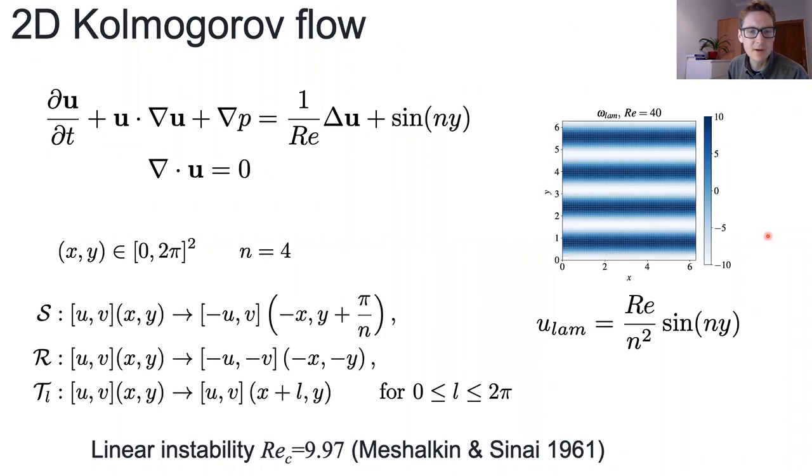So I'm going to study 2D Kolmogorov flow, which is the one that Chandler and Kerswell studied and has been studied quite widely for this type of thing in recent years. So basically it's a 2D Navier-Stokes flow with a sinusoidal body force, non-dimensionalized such that you have a Reynolds number appearing as your only control parameter. I'm considering square domains.